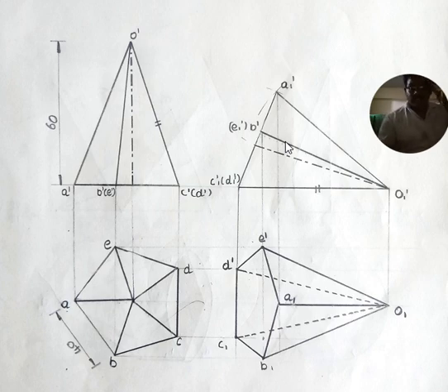Then we have to draw vertical projection lines from the second step front view and horizontal projection lines from the first step top view. Then we have to mark the intersecting points. After marking the five base corners and one apex intersecting parameters, we have to connect all the base sides and the slanting edges. Finally, we will get the final top view based on the given conditions.